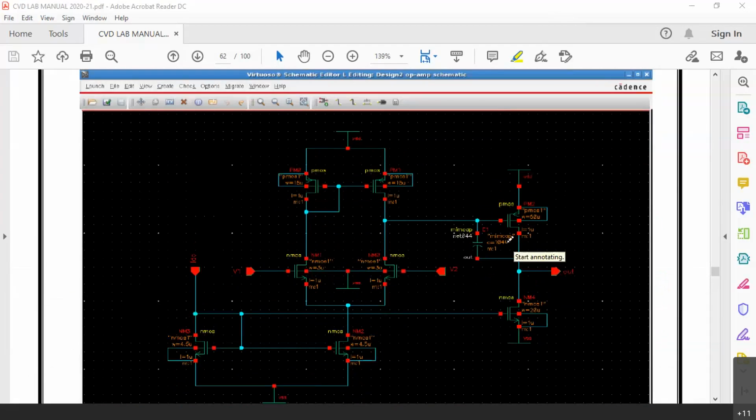In fact, Miller modeled the capacitance which was internal, right? Now here also you have the capacitance between gate and drain. You will have that capacitance inside. That is the parasitic capacitance. Between gate and source also, we will have a parasitic capacitance. MOSFET means always capacitances inside also. But for providing negative feedback, we have connected an external capacitance.